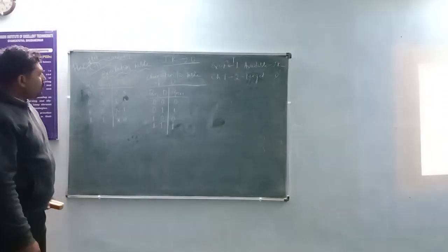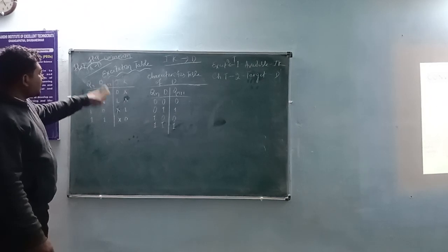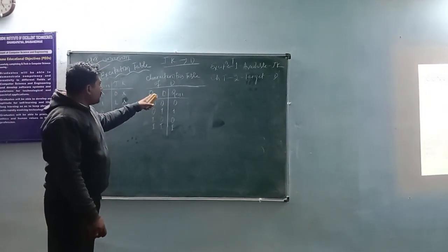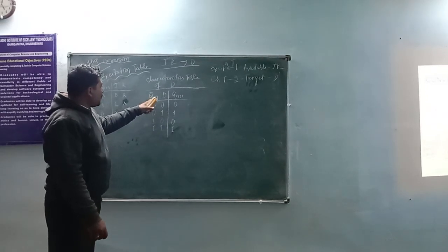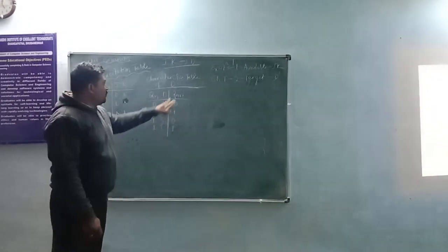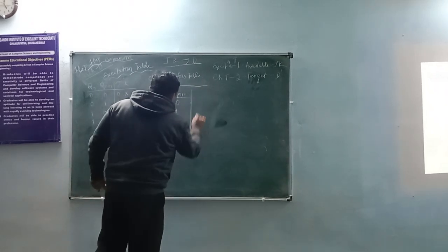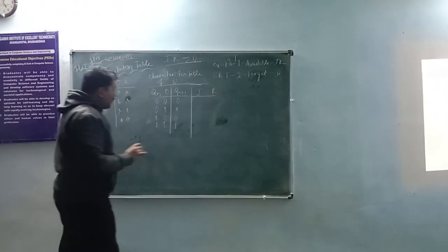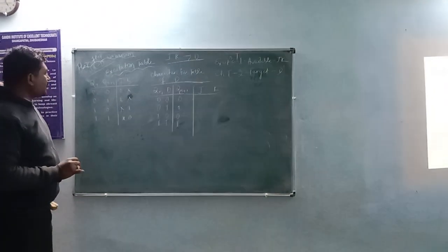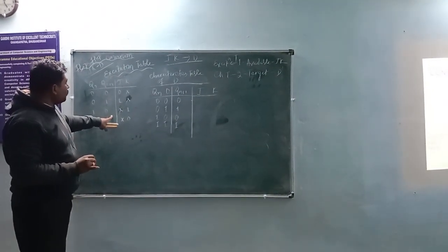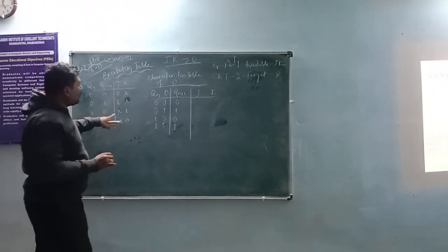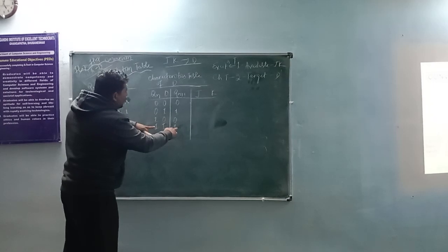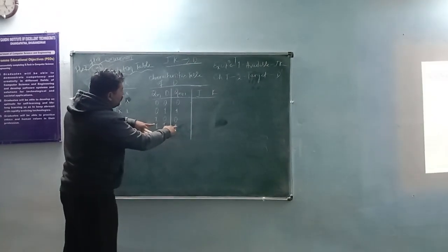So we are trying to find out the values of J and K with the help of this characteristic table, which is derived with D from its present state and the next state of D. So what I am writing here is J and K. I am trying to find out the values of J and K, referring to the excitation table of JK and the characteristic table with the present state Qn and future state Qn+1.